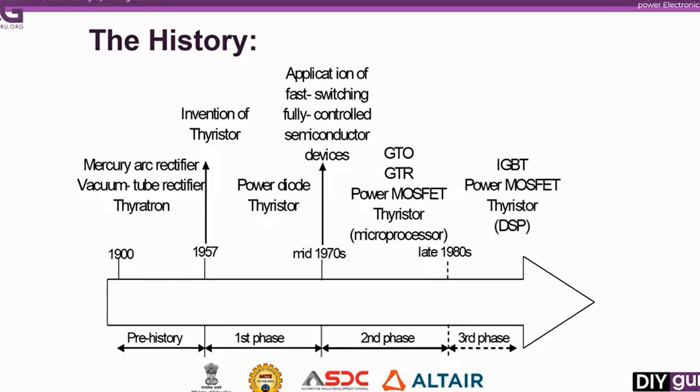The power MOSFET is the most common power device in the world due to its low gate drive power and fast switching speeds. But in 1982, the insulated gate bipolar transistor or IGBT was introduced. It became widely available in the 1990s. IGBTs have the power handling capability of the bipolar transistor and the advantages of isolated gate drive of the power MOSFETs. So the IGBT takes the best from both the bipolar transistors as well as the power MOSFETs, and includes them into the IGBTs.